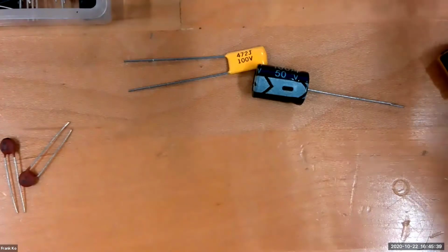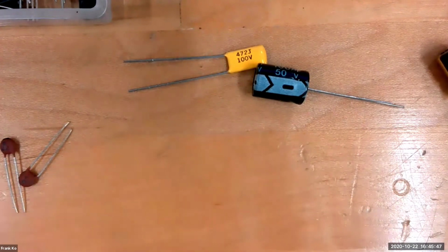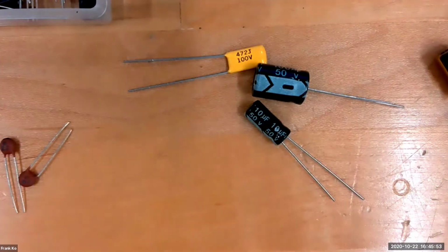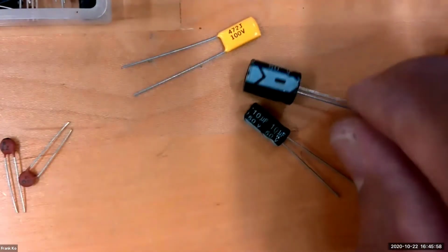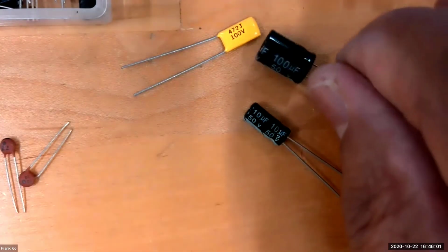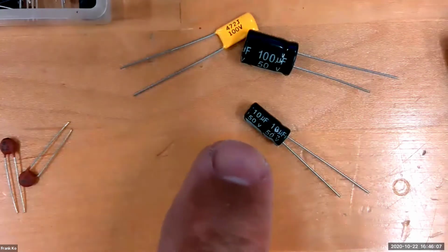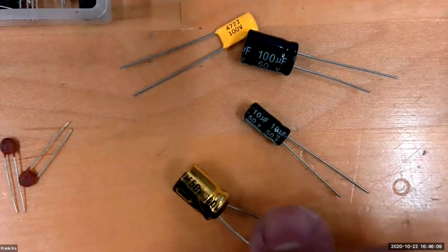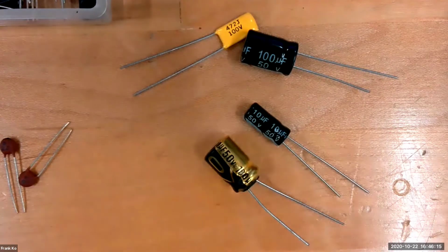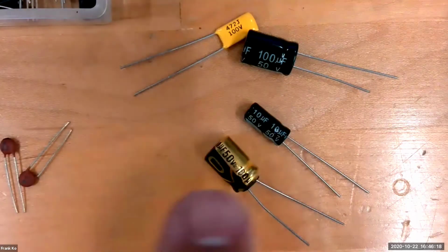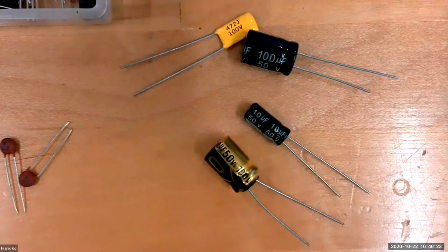We happen to have these guys. We happen to have this guy here. Flip it over to the other side maybe. Can everybody see the value of this particular guy? 10 µF, 10 microfarads, yes? So the first one we demonstrated was a 100 microfarad. This one's a 10 microfarad. This guy here from a different manufacturer, the marking happens to be right where the crimp ring is, but that's also 100 microfarads. So on the larger body capacitors, there's enough space for them to print a value that is easy for you to read.